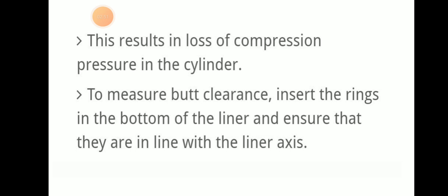To measure the butt clearance, we insert the ring in the bottom of the liner and ensure that it is in line with the liner axis.